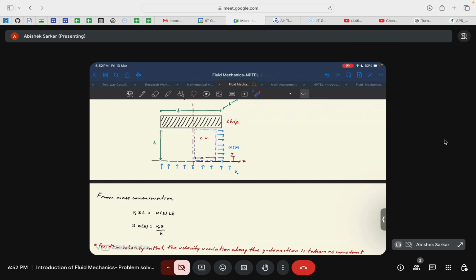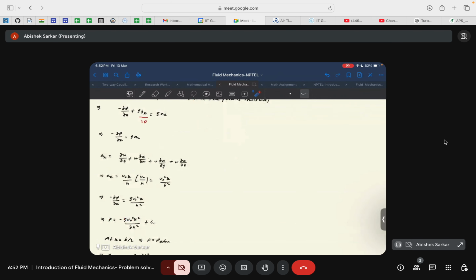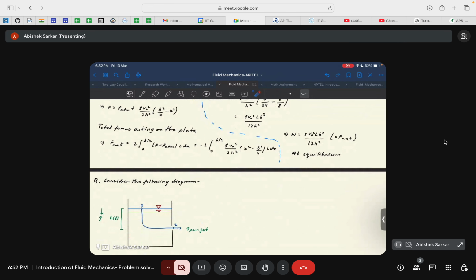Okay. So since the pressure on the upper surface of the plate is the atmospheric pressure, the pressure here has to be the excess over the atmospheric pressure. The pressure that we got from Euler's equation is indeed the absolute pressure, not the relative pressure. So for pressure times area, we take the relative pressure, or the gauge pressure in other words. We'll have the integration of 2 times 0 to b by 2 of P minus P ATM, the gauge pressure, times the area, that is L dx.